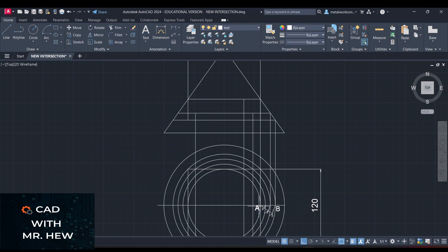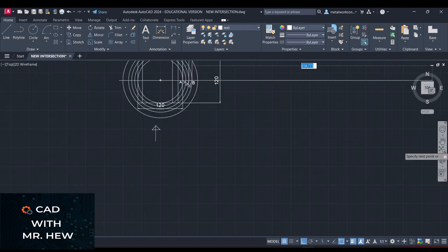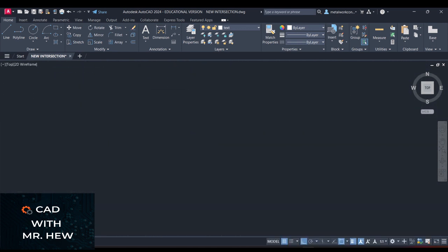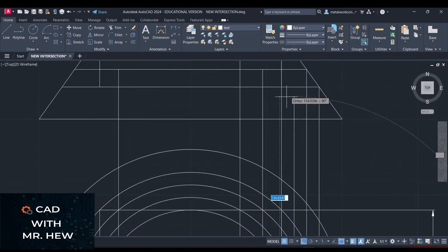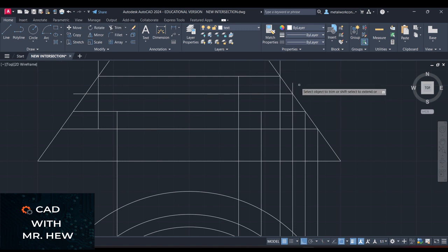So what I'm gonna do is project up the second disc, which is this number one right here, right? So look now. I projected this one, right? I need to project the line going up here. So let's do that now. Line here. Gonna go up. Look, gonna go up to the side of the cone to get the disc, which is there. Enter. We're gonna draw a horizontal line to represent the disc in the front elevation. Enter. We're gonna trim to let our drawings look neat and sharp.